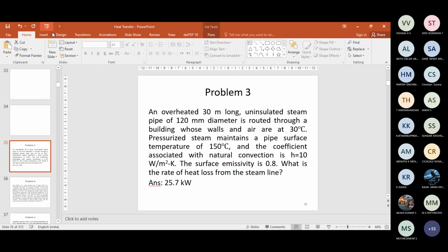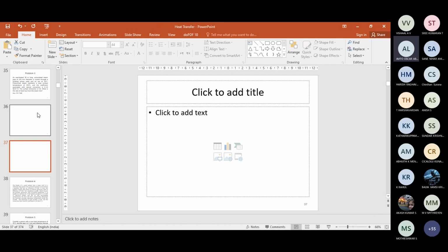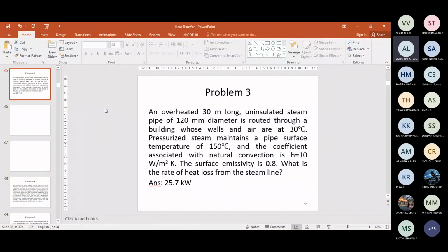So in the previous question, it said from the interior wall and the interior air. So why will the heat go in two directions? Will it not take only the net direction, whichever is higher minus lower in terms of temperature? Yeah, you're right. Since in this case we know the temperatures, we are very clear about the direction of the heat transfer. Sometimes when we are not clear of the temperature magnitudes, we may have to decide which way the heat transfer goes. So in the previous problem, there is only one way in which the heat transfer goes, from the inside to the wall and not the other way, because the wall is cooler than the ambient. Okay, sir. So that question is only to mislead you.